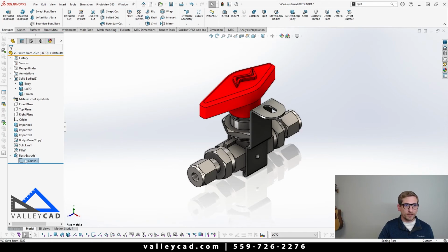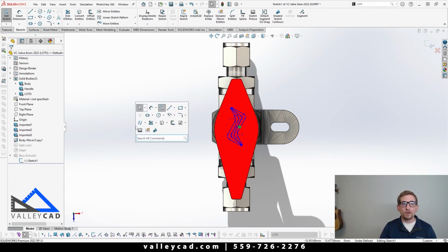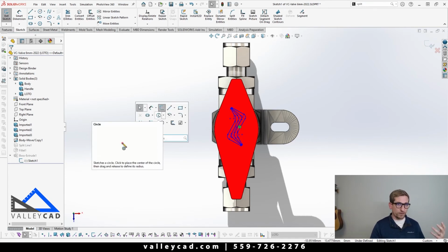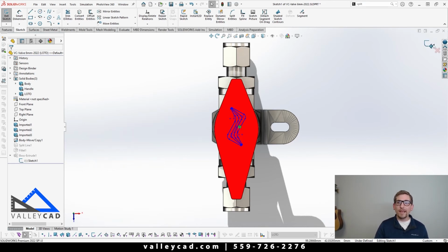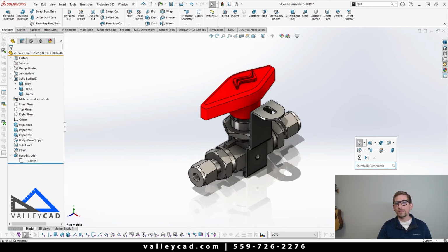And by the way, that shortcut command works on different variables based off of what sort of function you're in. So here I am inside of a sketch. If I push the letter S, here are all my functions for accessing sketch commands. Pretty cool. And assemblies has the same sort of thing too. So utilizing that S key for shortcut is very powerful, and it's even more powerful now that we can search commands with it.